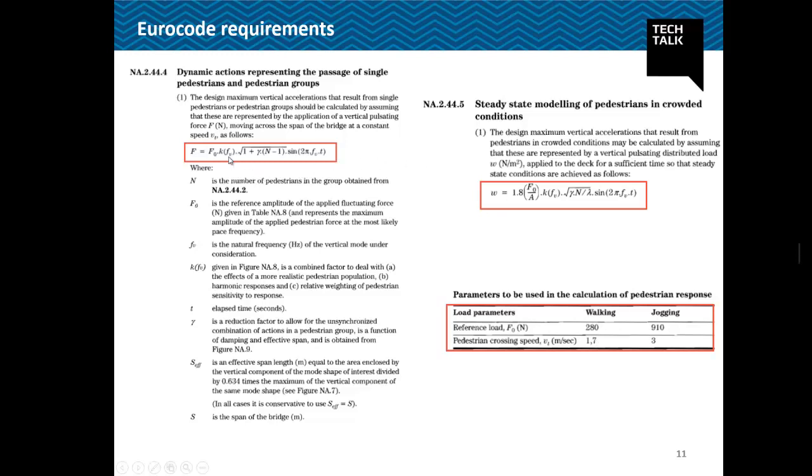And this frequency, we will be calculating this frequency. This frequency for loading we will keep the same as that which we obtained for the fundamental natural frequency of the structure. So basically what we will be doing is checking the structure for resonance condition. So we will be keeping the frequency of my load equal to the frequency of my structure, so that the resonance condition may occur.